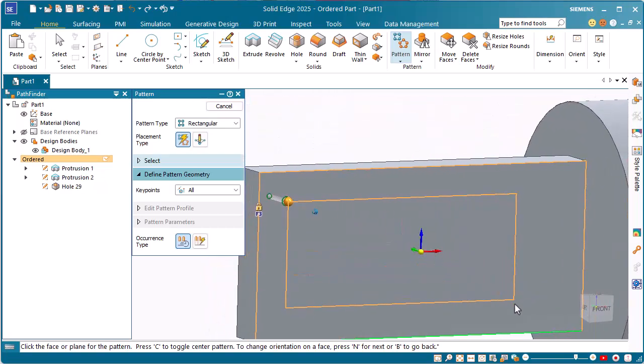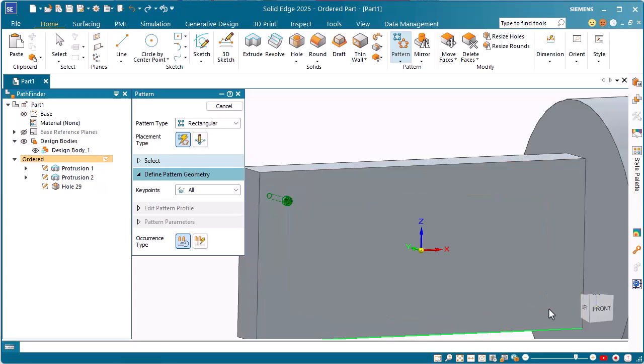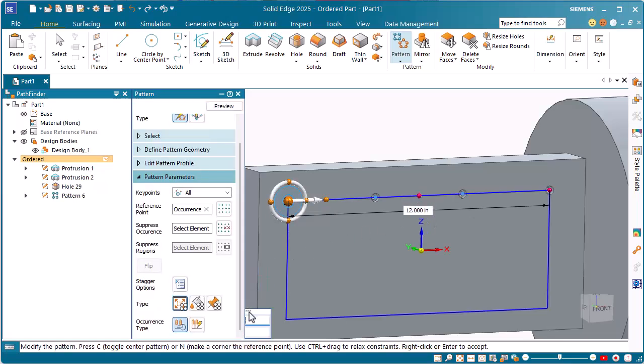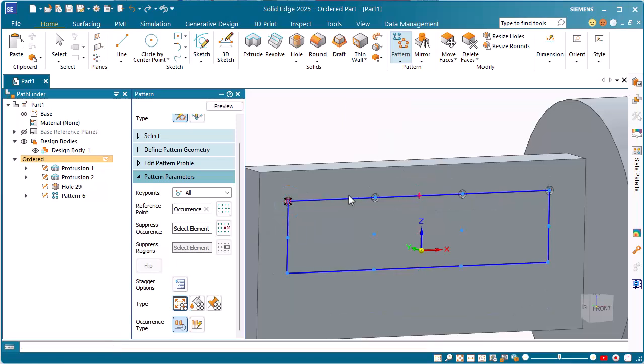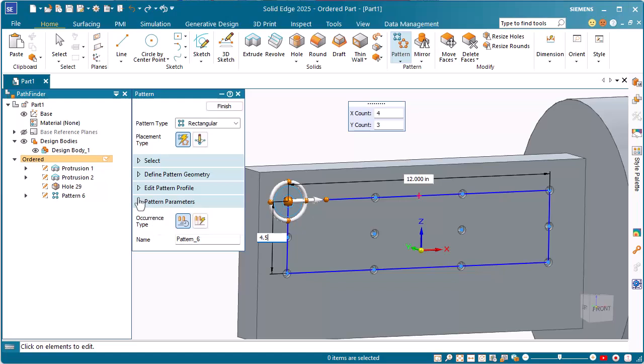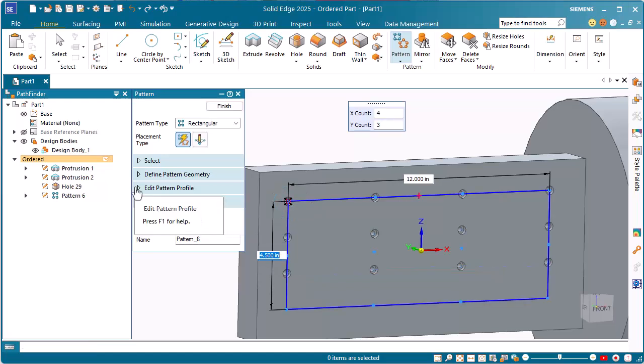So now I'll drag out my rectangle, and it'll come up with dimensions, so I could key in an overall dimension here. And if I slip this little dialog out from behind the command bar, I can key in another value in here to make this 3 and put in a number here, call it 4.5, and make sure that these other things are the way I want them to be.